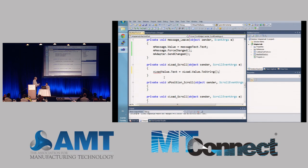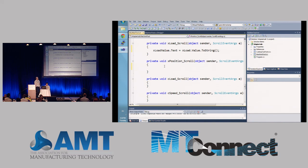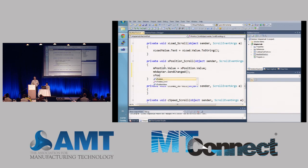So while he's doing that, we can talk a little bit more about the send change data. At the end of that gather routine, what that's doing is it's going through the data item list, checking each data item to see if it's changed value since the last time it was checked. It then takes the changed data items, and those are the data items that it actually sends the new information up to the agent. That cuts down on unnecessary network traffic. So we've really taken great pains to minimize network traffic.